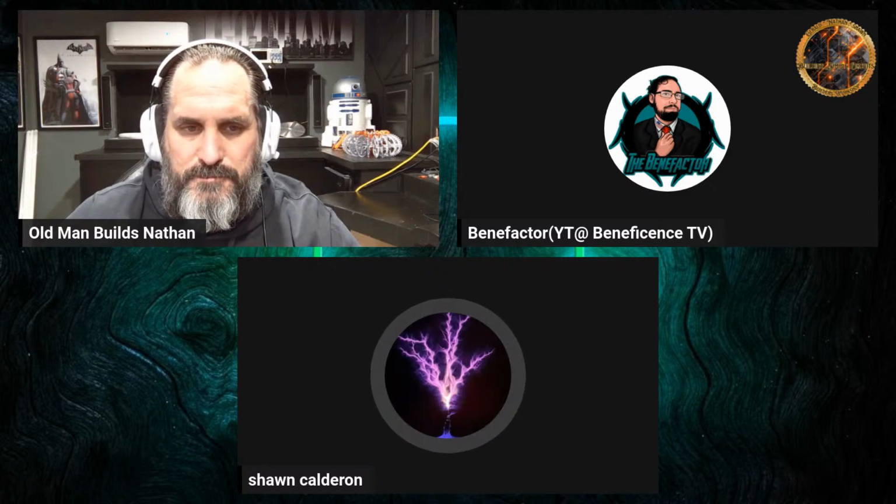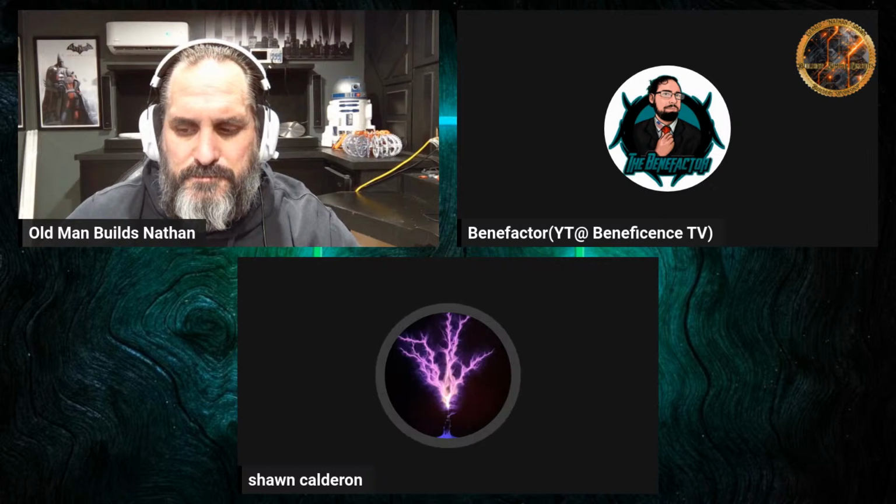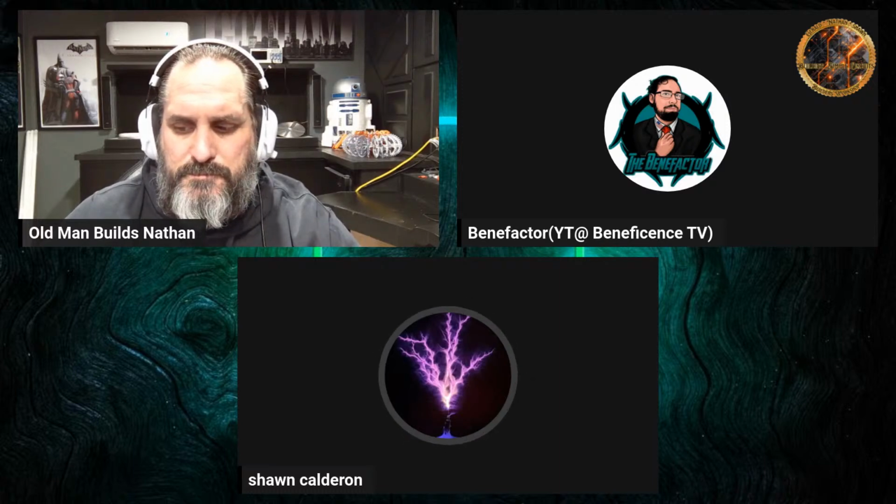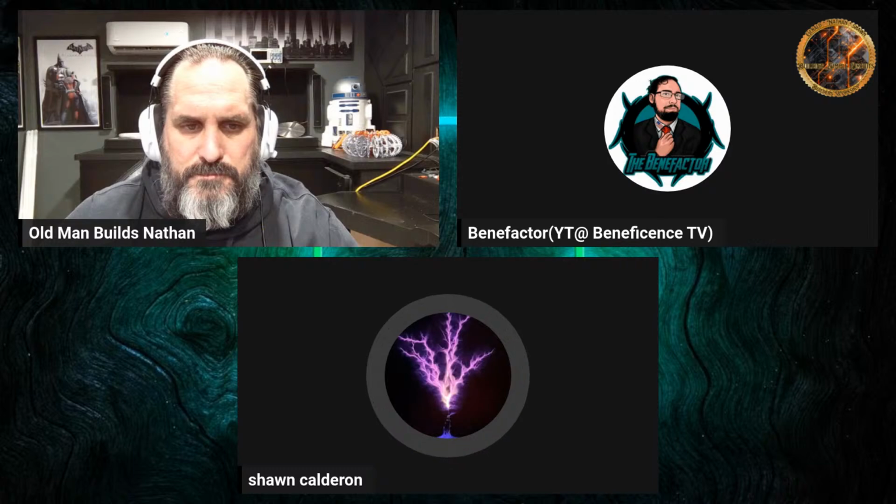Let's see, David Gruel. I will be running my ZVS with 4 transistors in parallel for each side of the driver. Yeah, that's cool. I'm running a 4 MOSFET or 4 transistor ZVS as well, though I have 2 transistors in series connected to 2 transistors in series. So it's 2 in parallel with 2. A slight change on that, but it'd be interesting to see how that goes. So if you could keep us up to date in the chat.